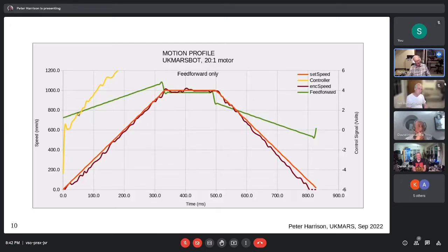And also for all of the intermediate speeds, for every speed in between, I can apply a voltage corresponding to the speed, and the robot does a remarkably good job of tracking my voltage profile. In fact, if you saw it run on the ground, you wouldn't be able to see the difference between this and the controlled output. It does very nearly 500 millimeters, and it does it at speeds which are remarkably close to the desired speed. But it's not actually under full control.